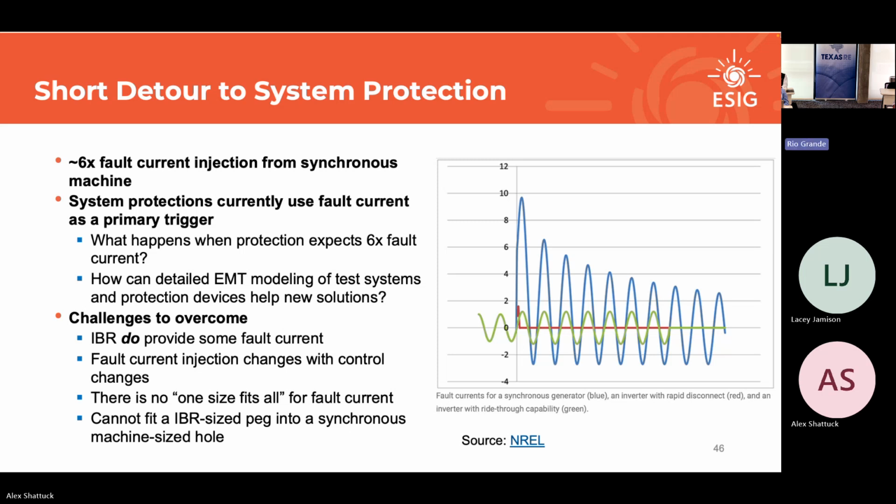If you ask a protection engineer to get you data from the field, you get it as found, as left, as expected. It's wild. It's fantastic, right? So you don't want to test out a new protection scheme on the fly. You're not going to go change the transmission relays and say, oh, that made sense, let's do it. Studying it in detail, with the real responses of an IBR and the response of the system, is extremely important.